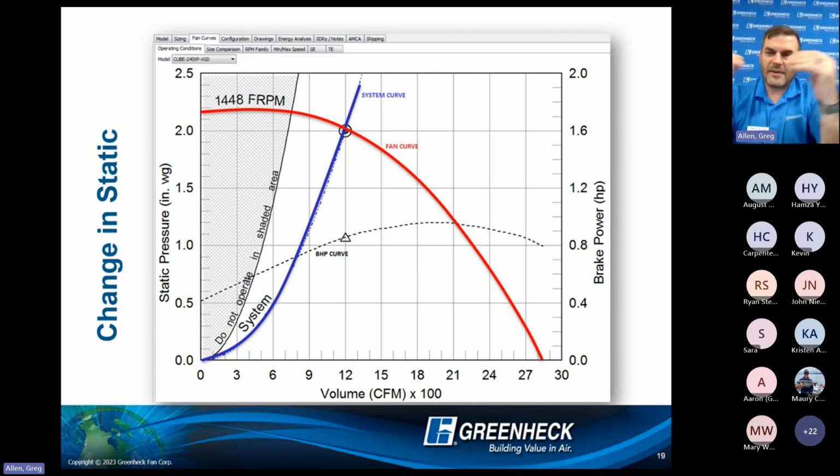That 2 inches represents all those elbows, the whole works. And then it's installed, and you go back to do a review, and in your as-built, the ductwork is going around a couple of columns. That was not in your design, right? So what's going to happen? Static pressure is going to be a little different than you added because you didn't account for those extra elbows.